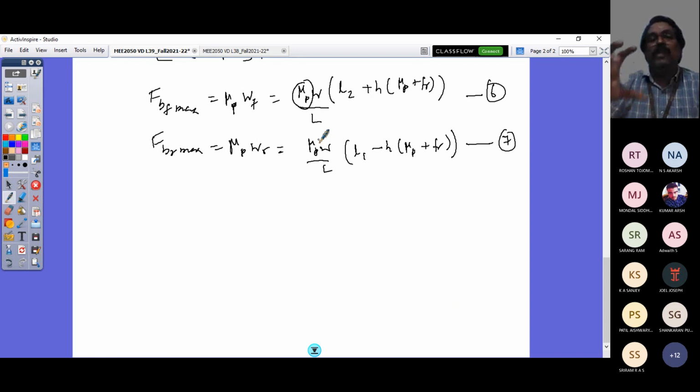There will be a wheel speed sensor that looks at what is happening when the brake system is applied, with a threshold value of the speed permitted. Accordingly, a signal is taken to a control unit, and then it goes to the brake cylinder, where the brake pressure can be modulated and so on. We will see that in detail, the characteristics of ABS requirements and the different types of ABS systems in a two-axle vehicle, in the next class.